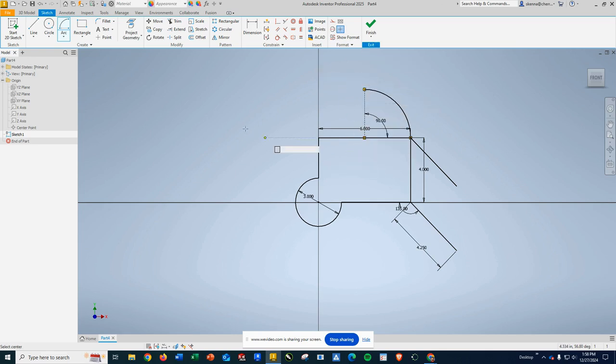You'll see that basically what it did was it created a construction line here. So this is a line for construction, as you can see in the format area, it's right here. Okay, that's a construction line. And it created it as 90 degrees. It defined the center as the midpoint of this upper arc, and that's how I created it. So anytime you know the center and where something should start or end, or where something should start and the angle necessary, go ahead and use the center point arc. This is really useful. You could also have overdrawn this by just selecting a point and then maybe used a different line or something to trim it back where it needs to be.